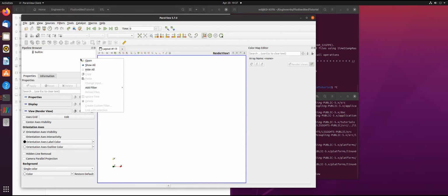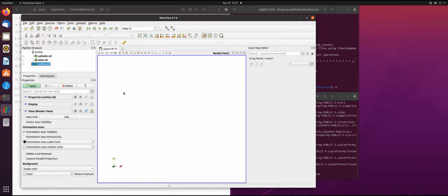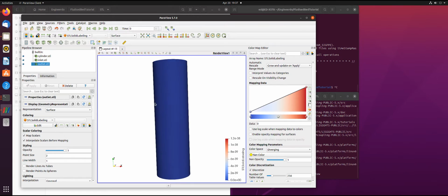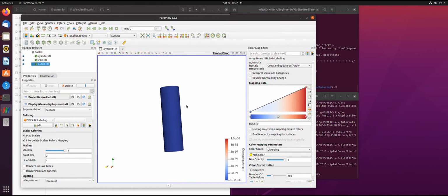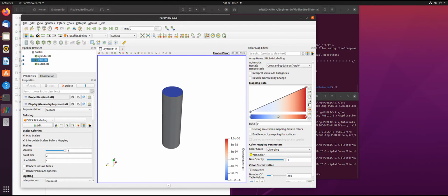What you can see here is a cylinder, closed on both ends with a lid. I can use a little eye symbol in ParaView to make the structures invisible. You can see now that the cylinder is closed by an outlet and an inlet. These structures, the inlet, the outlet and the cylinder, are used in OpenFOAM for the boundary conditions and the automatic meshing with snappyHexMesh. They are also used in the DEM simulation, where they will function as the walls.